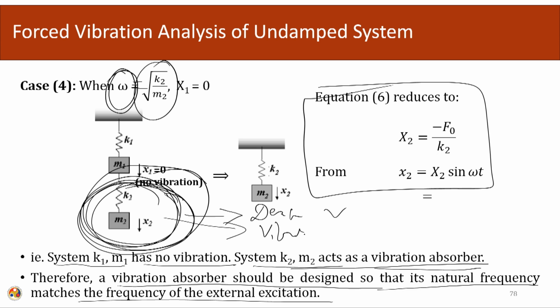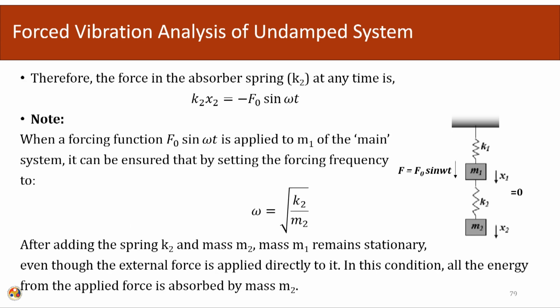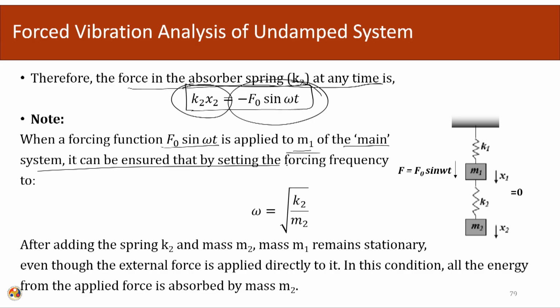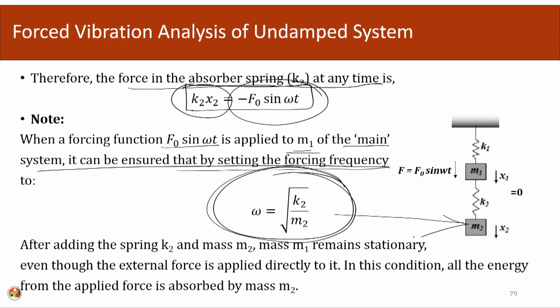The force in the absorber spring at any time is given by this quantity, because this is the displacement quantity and this is the forcing function quantity. So, when a sinusoidal forcing function is applied to M1 of the main system, it can be ensured, by setting the forcing frequency to this particular value, that the forcing frequency is set to the vibration frequency of the absorber system.